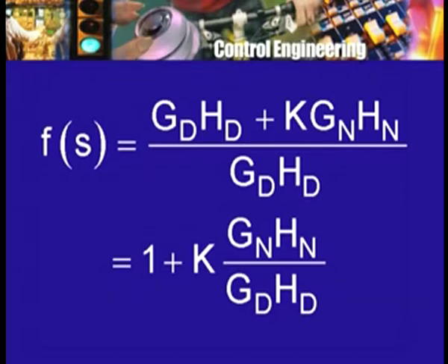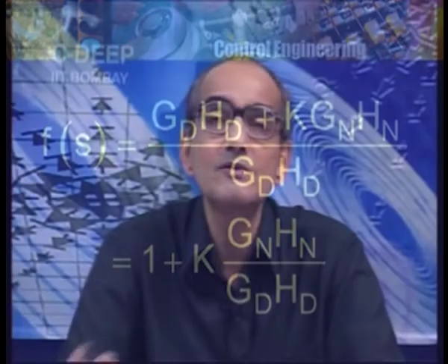Now, we are going to apply the Cauchy principle of the argument to this function f, and why? Because the numerator of it is the characteristic polynomial. Unfortunately, we do not know where the roots of the characteristic polynomial lie for different values of k. We can calculate them using Routh, we can even calculate some special intersection points and so on, but in general, if you do not use the root locus approach, we just do not know where the roots of this characteristic polynomial are going to be.